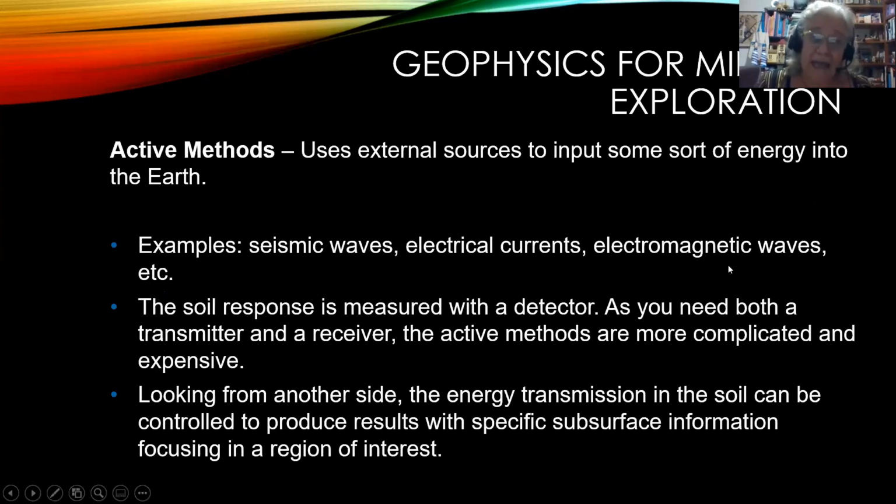And we have the active methods that use external sources to input some sort of energy into the earth, like seismic waves, electrical currents, electromagnetic waves, etc. So the soil response is measured with a detector, and you need both a transmitter and a receiver. Those methods are more complicated and expensive.